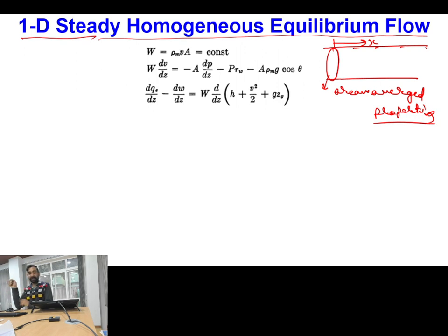And at the same point of time, because the major idea of homogeneous flow theory is that we have to go with the mixture properties, I have to write over here combined phase equations. Is this point clear? Combined phase means if I write individual phase equations and take their sum, then whatever the equation I get, that is nothing but for all the phases present in the system.